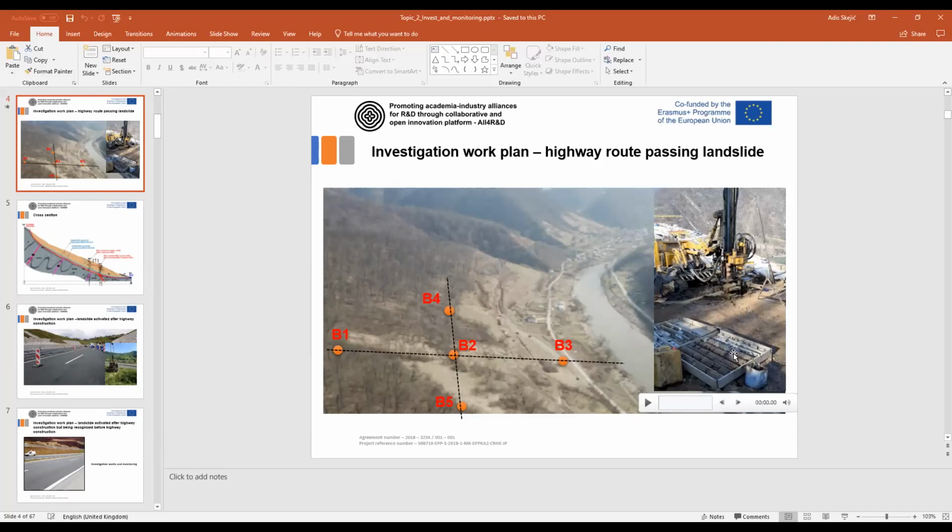Yes, thank you. And I have another question. You mentioned piezometers, inclinometers, and extensometers. Briefly, the piezometers show us the pore pressure and the groundwater level, right? Okay, that's right. The inclinometers show us the horizontal displacement, and in any depth along the borehole.